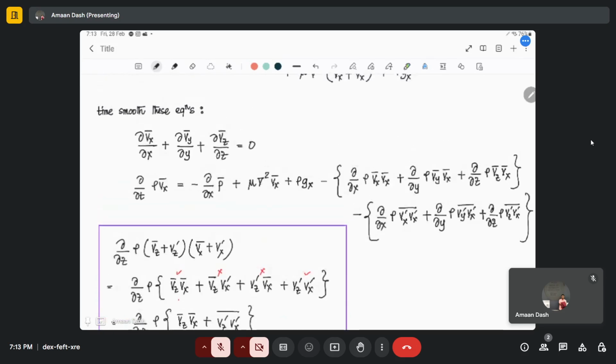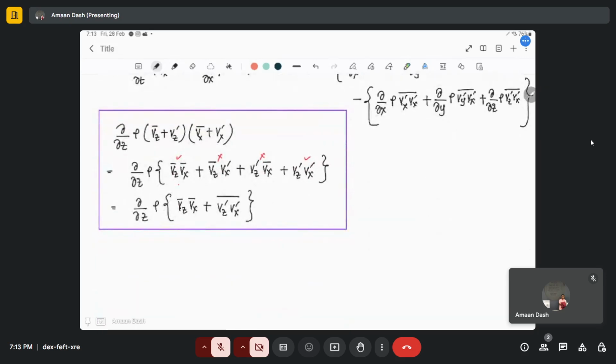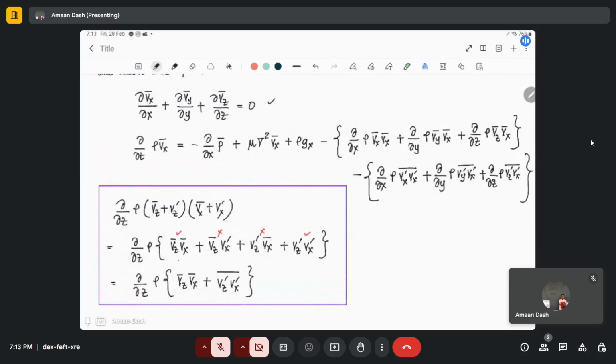So these are the time smooth expressions for the equation of motion. So what we see is that this continuity equation is the same as what we already previously had, only Vx is changed to V bar, Vy to V bar, something like this. The equation of motion has V bar and P bar components, where we previously had V and P. In addition, there appear to be dashed underlined terms which describe the momentum transport associated with the turbulent fluctuations.